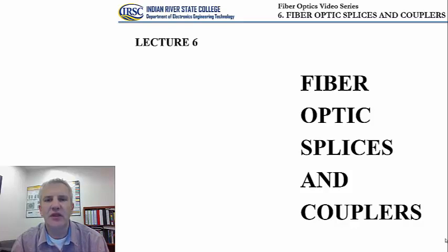We explained the fusion splicer as a device that's being used to perform the action of fusion splicing. We covered in detail different steps that you should go through during fusion splicing, such as the alignment, applying the high arc to melt the glass, and finally checking for a loss in a previously established fusion splice.